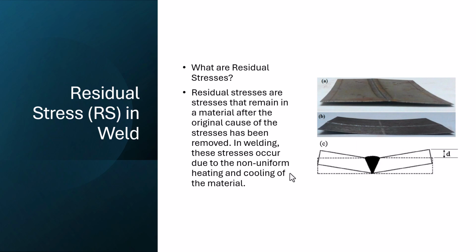If we look at this welded shape, you see the material was clamped in the grip, for instance. The material is melted and needs to cool down slowly, and it wants to expand or contract, and the grips don't let it do that, and as a result it is going to distort and become a shape like this.